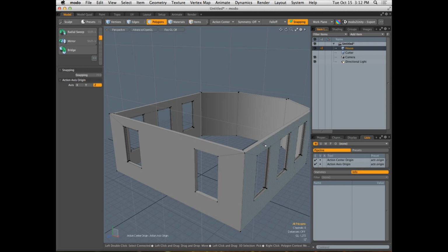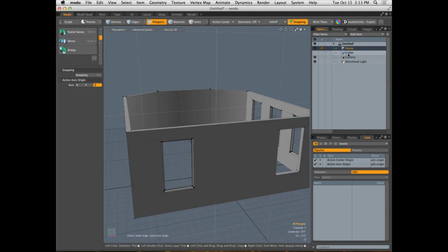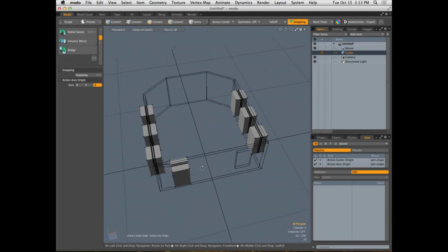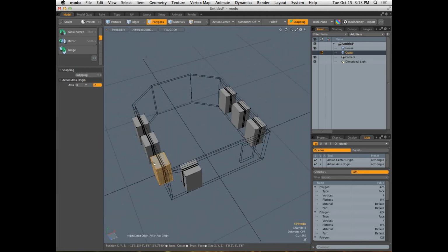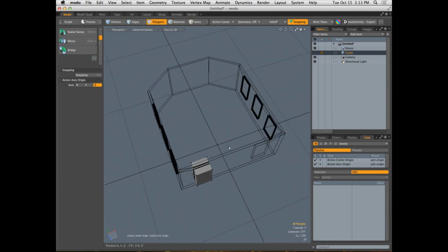How do you cut the squares out again? So the Booleans, let's do the Booleans one more time. Yeah, so I need a door. I need a door to my house, okay? I need a door, so let's iron out the door. I'm going to go back to my cutter geometry, and I'm going to delete almost all of these. I want to keep one just for me, because it's going to allow me to do something else here in a minute.